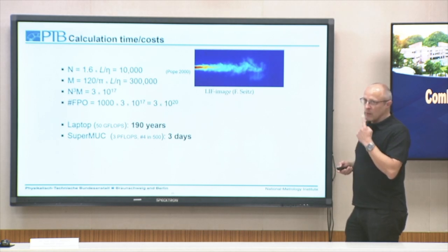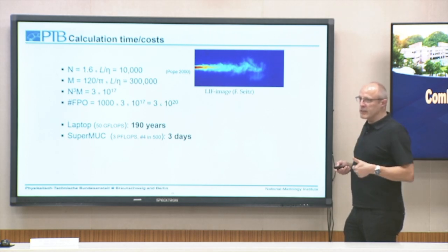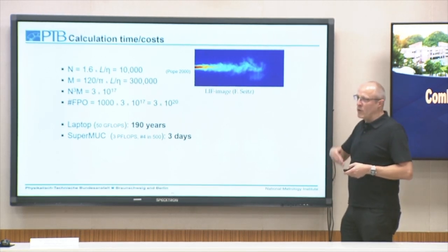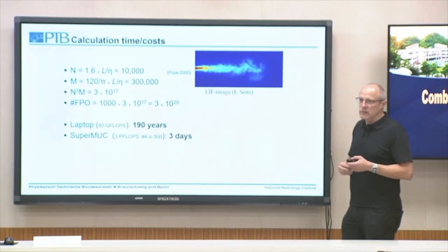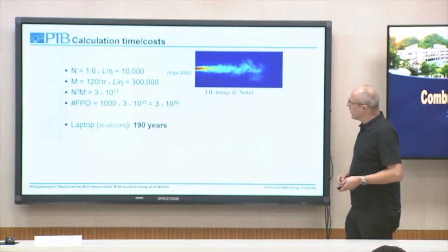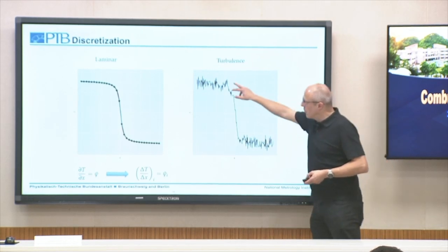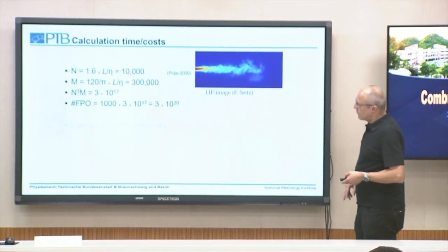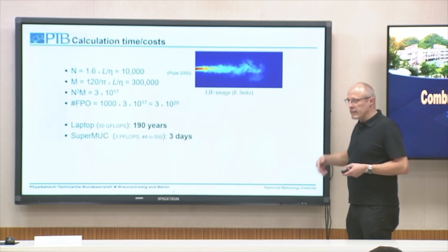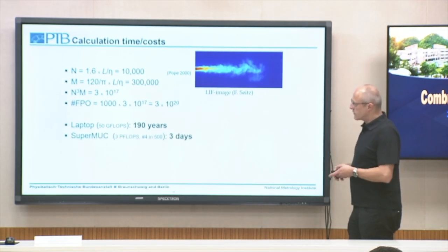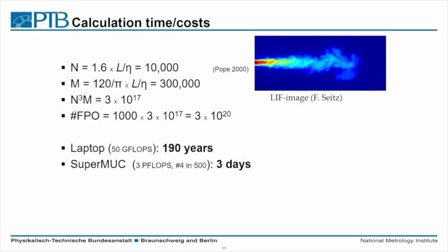But then you have to remember that that's one possible realization. We have a turbulent flow field. Normally we have to perform the calculations with small changes in the initial conditions to examine these effects more in detail here. So you have to perform several calculations with nearly identical initial conditions. So it still takes some weeks until you get your results.